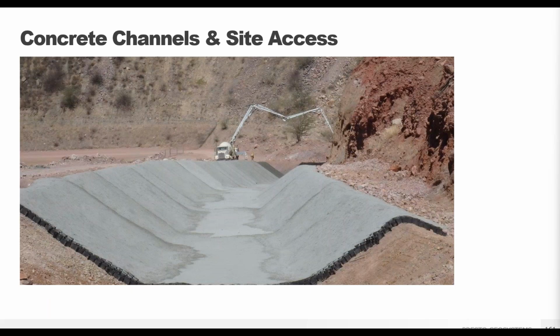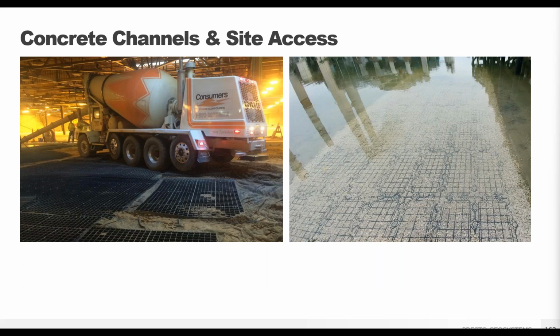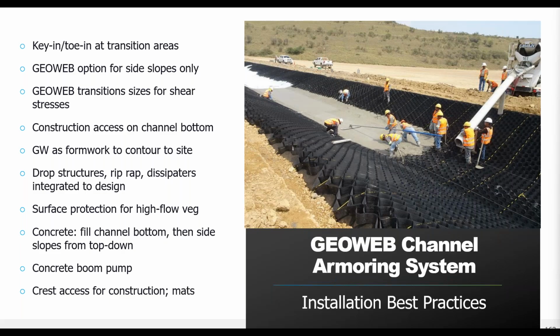A pro tip for concrete channel infill is to use a concrete boom pump, as you see here, or a line pump if you have an install easily accessed horizontally. Another important consideration and technique tip is to include site access along the channel crest that can support the loading of cement trucks and other heavy equipment. Temporary access mats can help if design constraints will not permit access as part of your design, and can even be placed in the water.